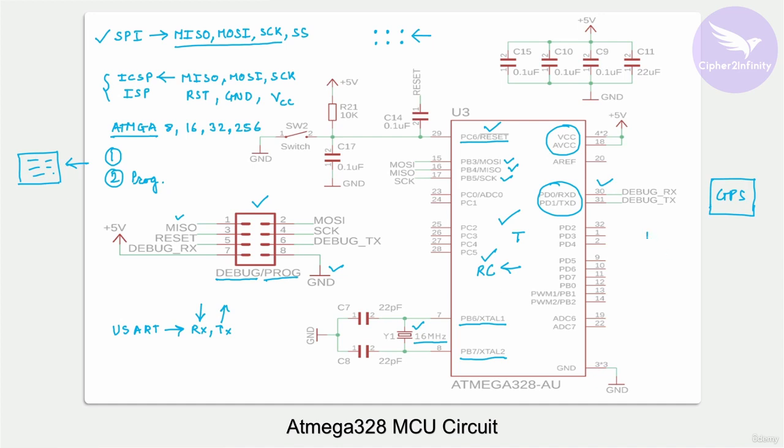For example, you can go for a 4 megahertz crystal. You can go for an 8 megahertz crystal. So I want to interrupt at this point. This RC oscillator which is there inside the microcontroller, its frequency is 8 megahertz. Okay. So remember that point.